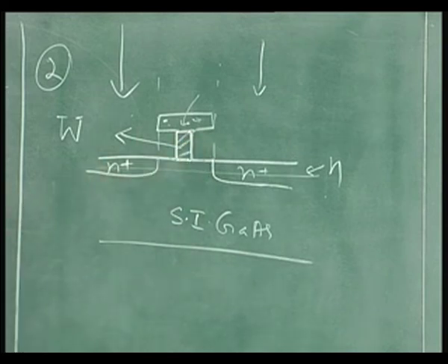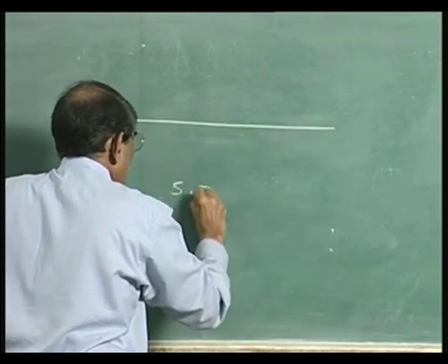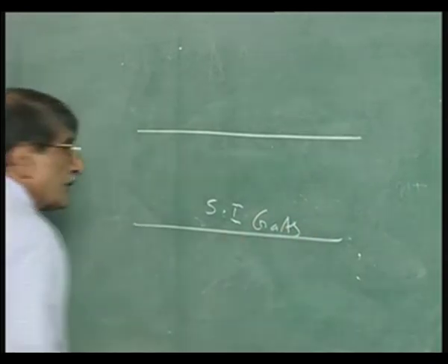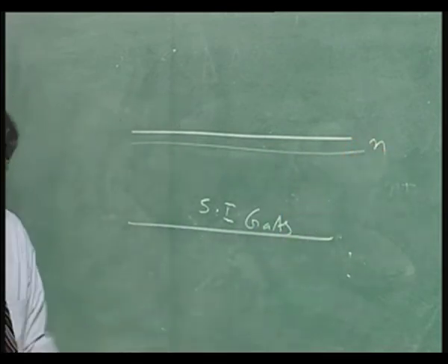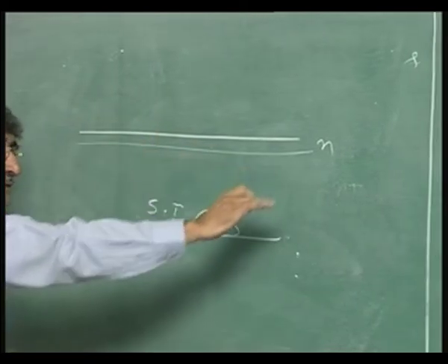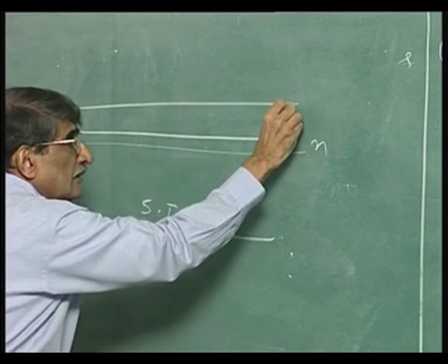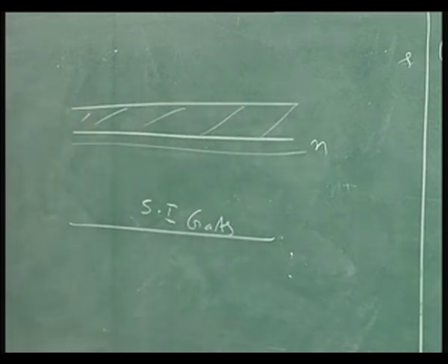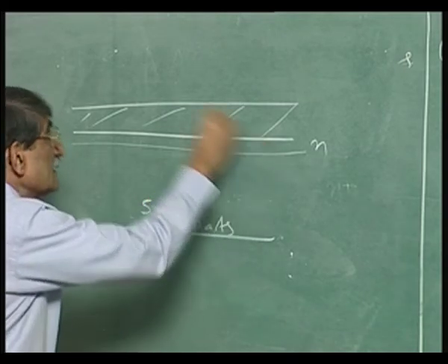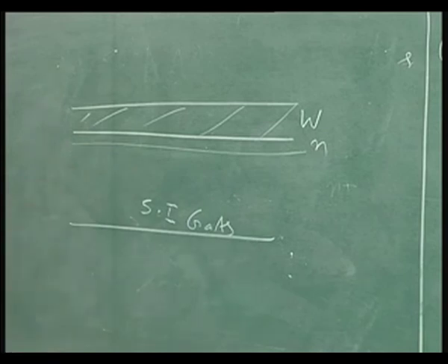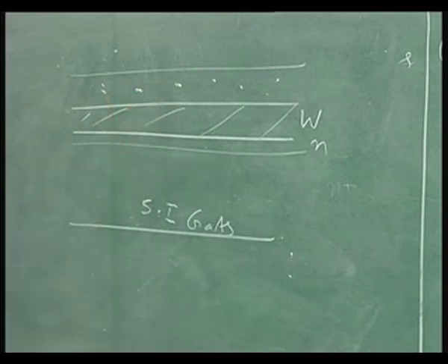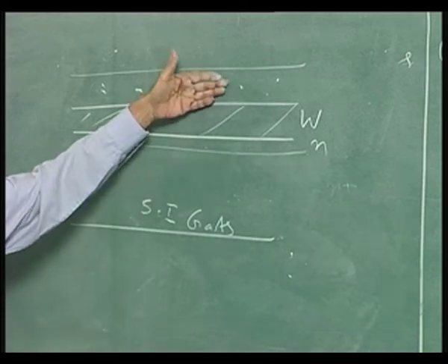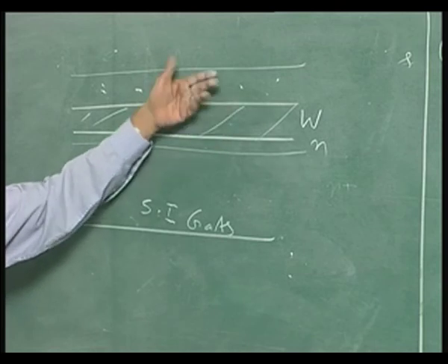So, there it is made, they make it on semi insulating gallium arsenide. Just going through how they do that. Then you have an N layer put or implanted, and then deposit tungsten all over. You can deposit it all over, and this is tungsten. On top of that, put that second material. This can be photoresist, or you can use aluminum metal, because when you etch this one, the etchant should not attack that.